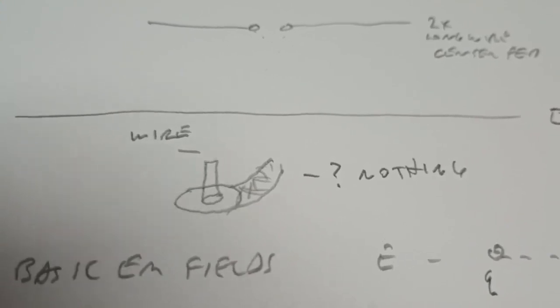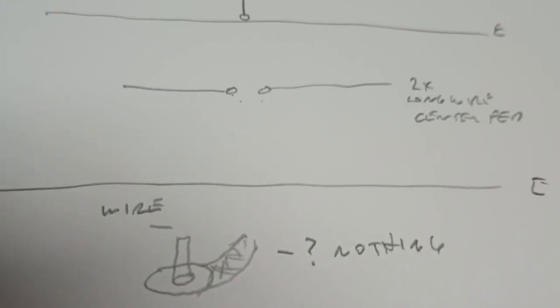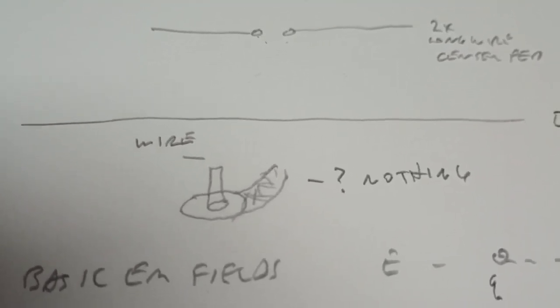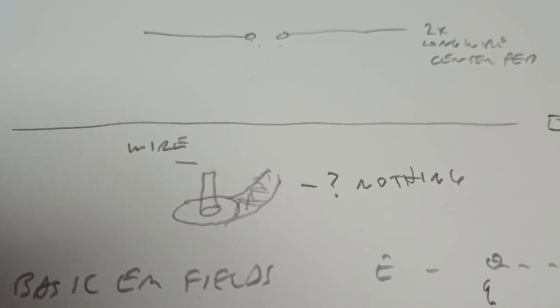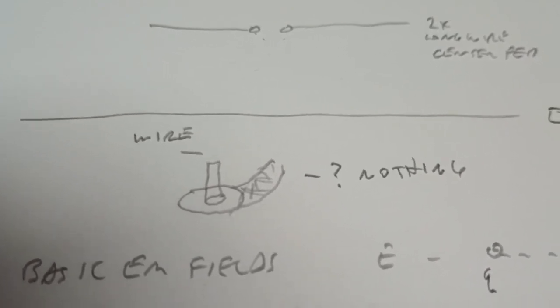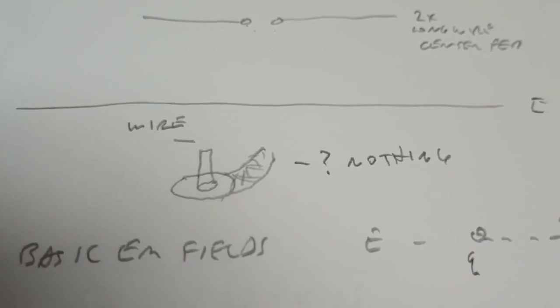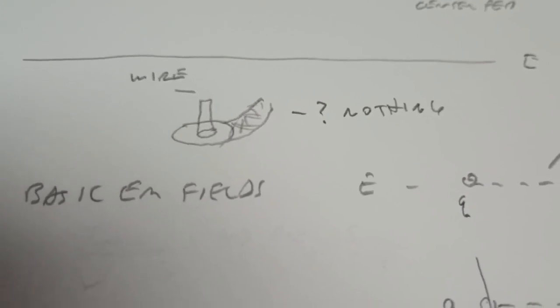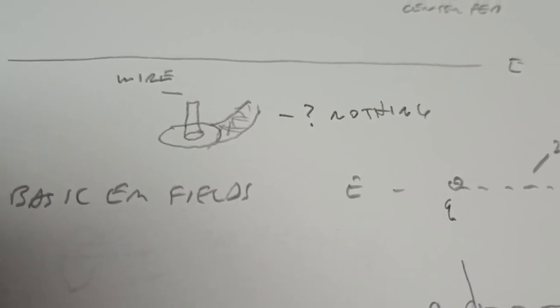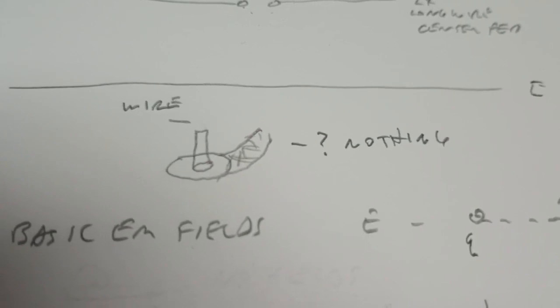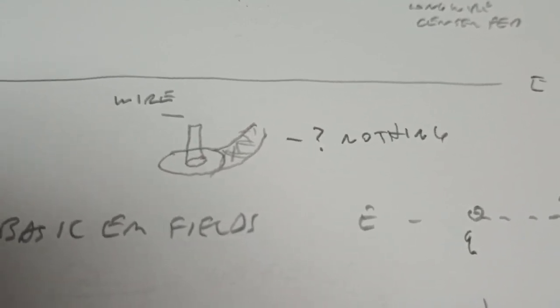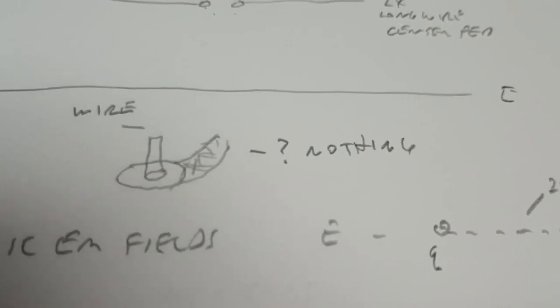So the problem is a shield has nowhere to go. It does in a dipole. It has two absolutely identical arms, and it works beautifully. I've proven that in my videos here. So if we're looking in the context that most antenna system analysis is done in transmit, because we have a lot of energy to work with for measuring, if an RF signal is coming out of the transmission line to this point, it hasn't yet reached the antenna. There's no antenna here. And it doesn't go any further because the shield has nowhere to go.